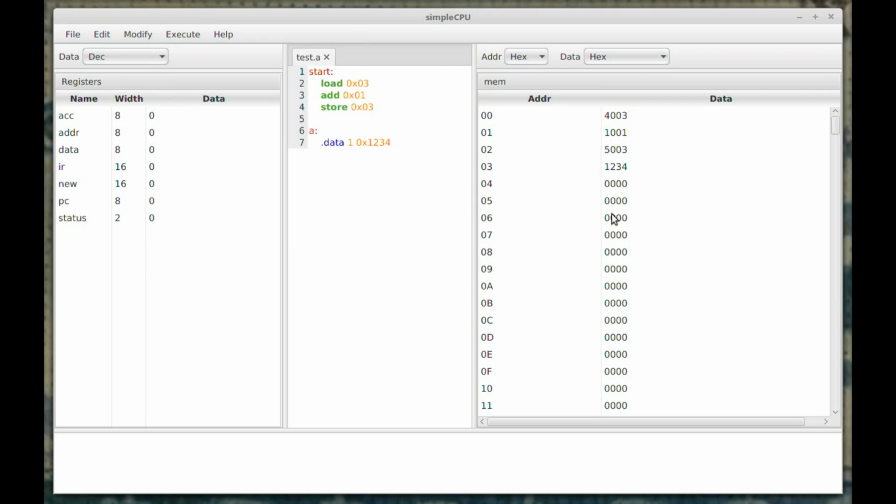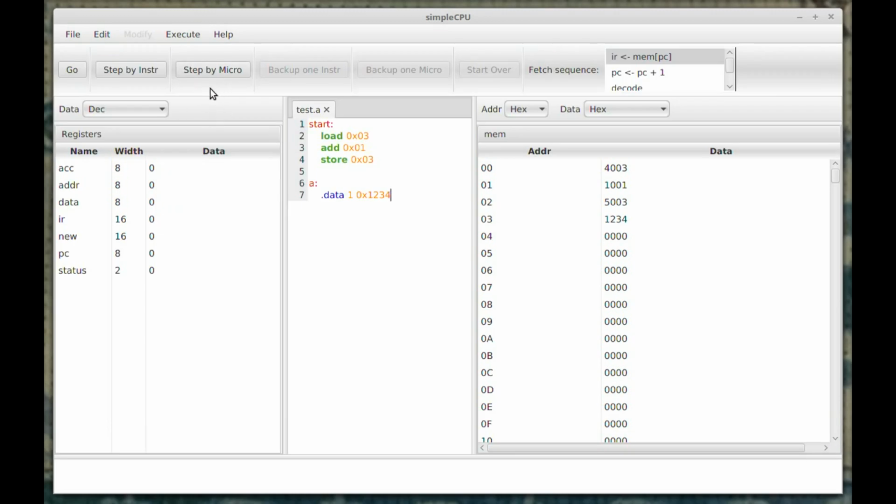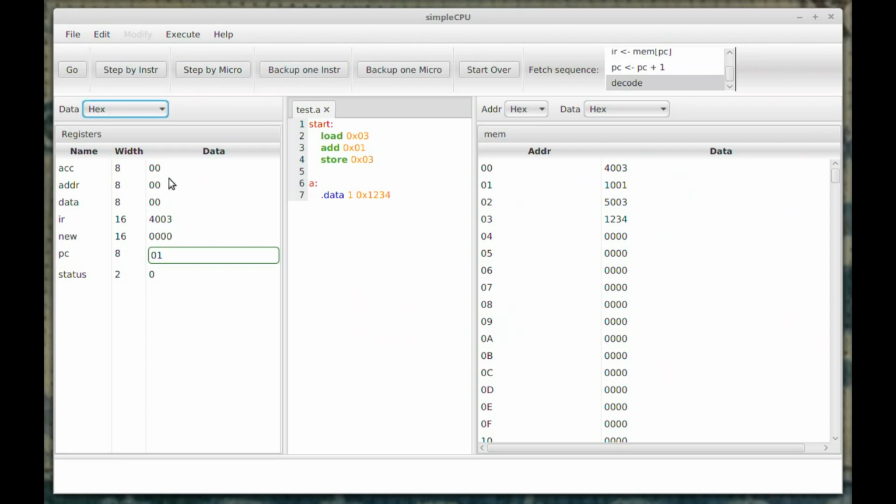So in the previous example where we defined the .data, we're actually defining the machine code that will be loaded into memory. And if we execute that program, as always, stepping through at the microinstruction level, we'll see we execute our standard fetch. I'd always recommend placing the displays in hexadecimal. That allows you to see the opcode field, which is the top nibble, and the operand field, which is the lower 2 nibbles, your 8-bit value. If you use a decimal representation, it's not clear what that particular value is representing as an instruction, so always use hexadecimal.